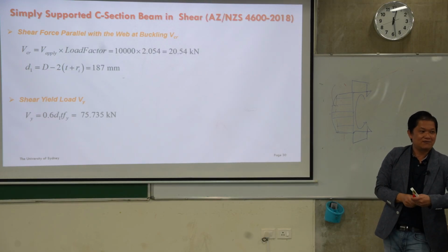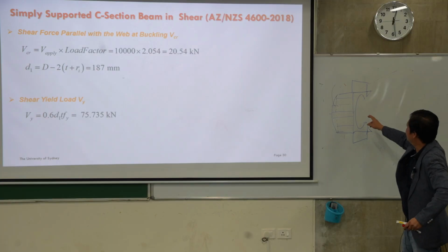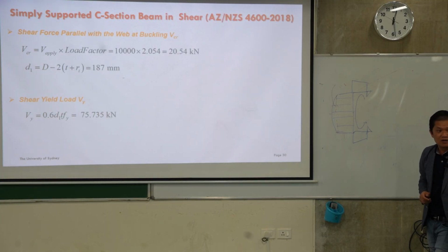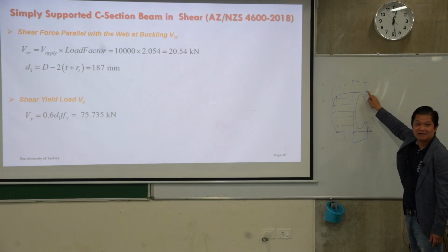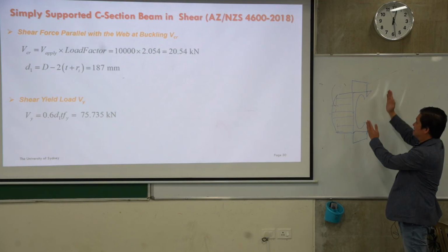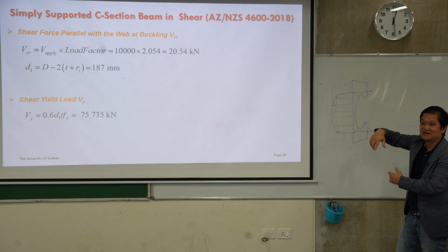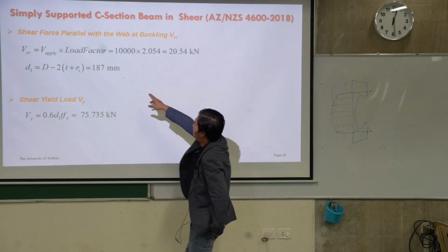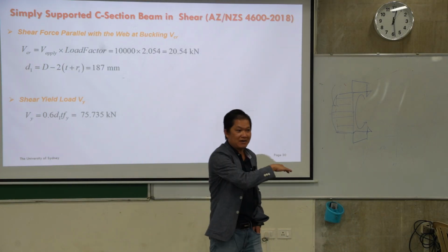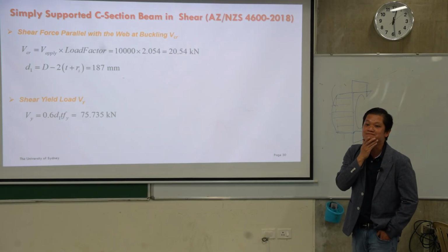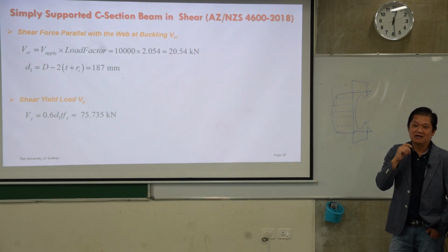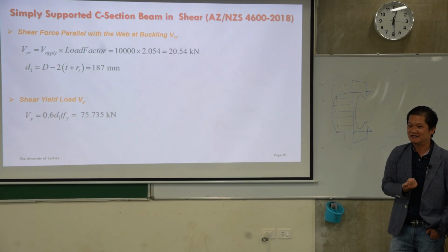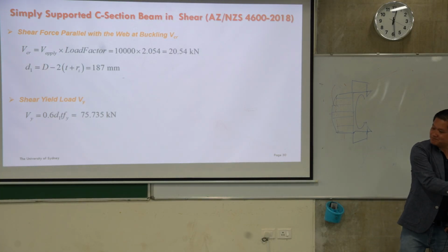So a little bit tricky, not much different here, and even a little bit more complicated if you want to take into account this bit of area here as well. It's actually the other way around. It goes up, the shear flow. So if you take into account the stress, it's a little bit more complicated. But if you calculate straight away from load, you just bypass that. You get the buckling load straight away from the eigenvalue. You run the analysis, you get a load factor, times it with whatever load you put in, that is very critical. How simple is that? Okay? It's good.